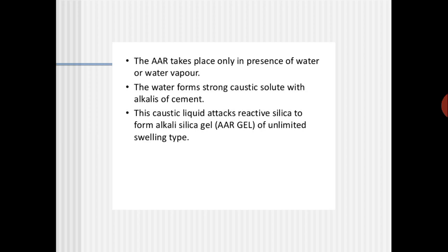So this AAR, that is alkali aggregate reaction, occurs only in the presence of water and water vapors. Of course, without the moisture content the reaction will not happen. The water forms a strong caustic solute with the alkali of the cement, that is nothing but the gel. This caustic liquid attacks the reactive silica to form a silica gel of unlimited swelling type. Normally the swelling is a continuous process, and it is not going to end.